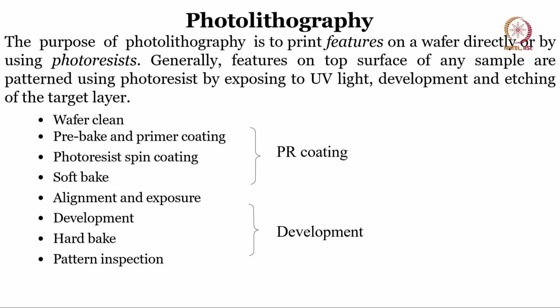So, the first step that we will use is cleaning of the wafer, right. This cleaning of the wafer is called RCA 1 and RCA 2 cleaning, okay. RCA stands for Radio Corporation of America.